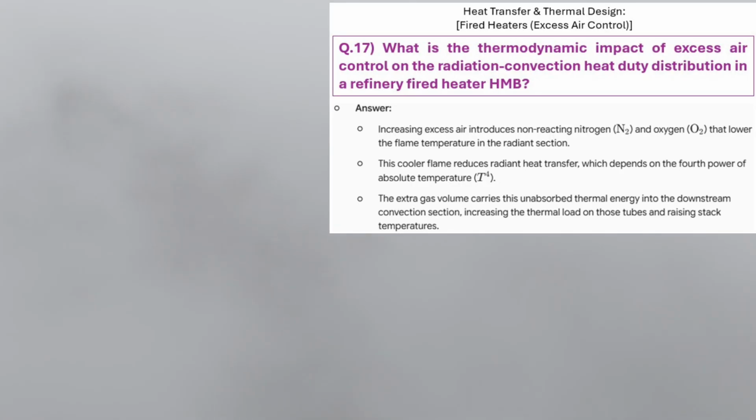That displaced thermal load shifts upward, aggressively pushing localized steam superheater tubes past their strict metallurgical limits. And conversely, you can't overcorrect and run below a 5% margin. Absolutely not. That instantly leads to localized oxygen starvation and the immediate generation of explosive carbon monoxide and heavy carbon smoke. We have reached segment 5, degradation and operational maintenance.